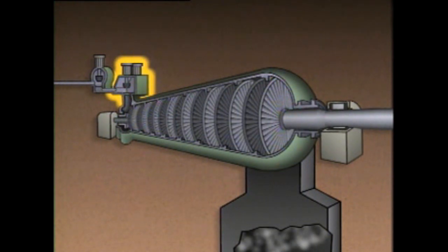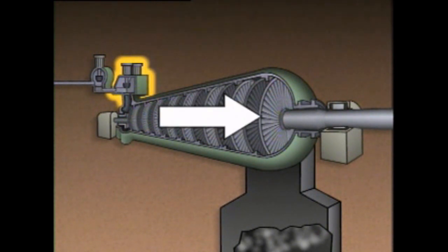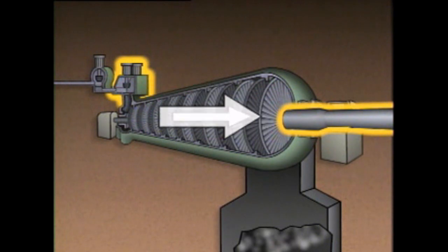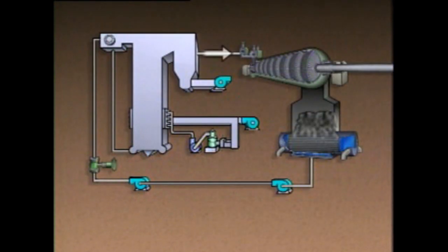If more power is needed from the generator, the valves are opened wider. This causes more steam to flow through the turbine, more mechanical energy to be received by the generator, and more electric power to be produced. The reverse occurs when the steam control valves are closed down more. When the steam flow is varied, the feed water flow to the boiler must be varied equally.